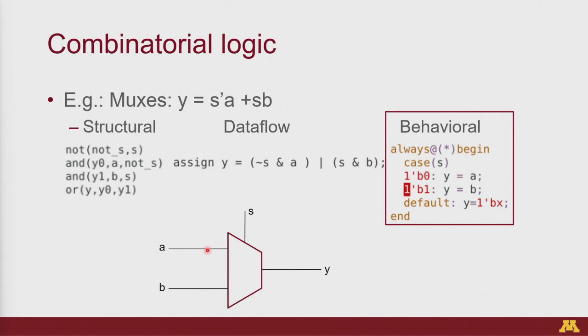That is what you call a priority case. But usually when you write a complete case like this, the synthesis tool will assume you meant it to be a multiplexer. It would assume that all your conditions are mutually exclusive, which it is in this case, right? That is the true case of a multiplexer.